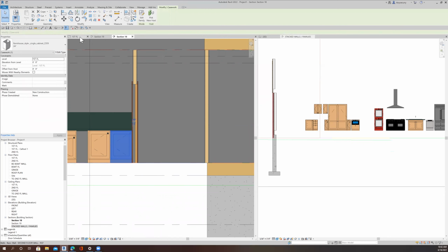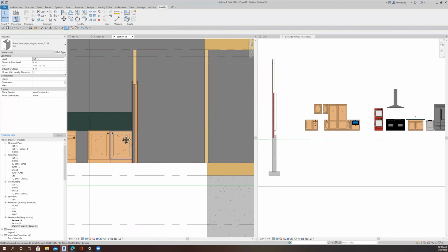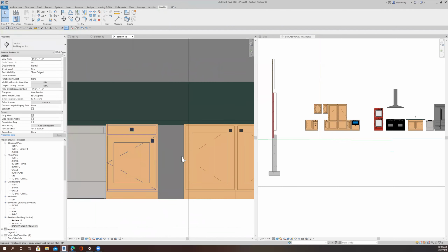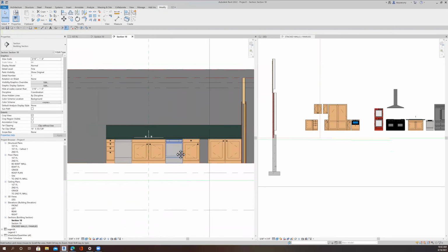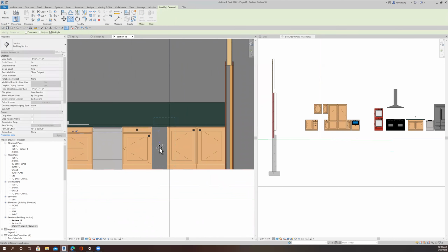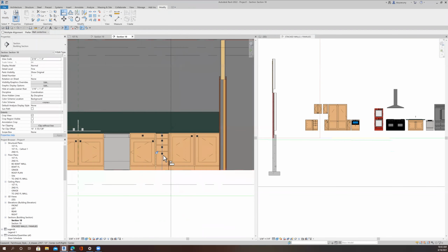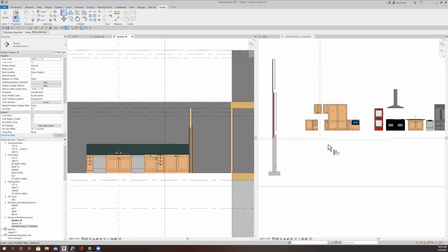If I click on this, go to the first floor, I can switch it. Just switch it like that. So let's go back to the view now and see what happened. When I click that arrow, it flipped it. Okay. And I still have a space here, which I want to put another set of these in. So we'll just copy that. From here, straight across, measure the distance that we have to fit inside. 1 foot, that's actually good. We'll align this guy right here. There we go.